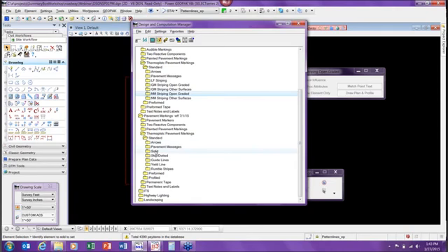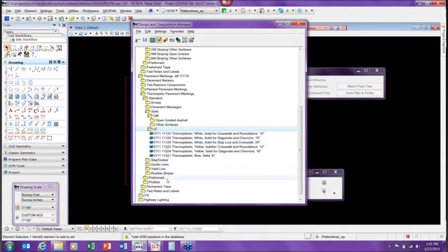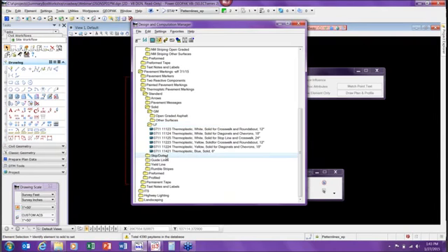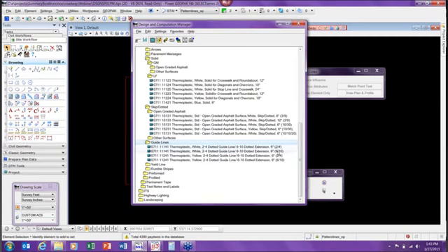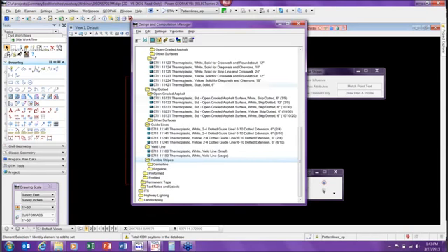So I've changed this up so that now you have a category for solid markings, my gross mile solid markings and linear foot markings. Then I have this skip dotted, which is my 3-9 and 10-30 skips. And then I have the guidelines, which is your 2-4 and 6-10 markings. And then the yield lines, I've just pulled that out, so it's in line with the type of marking.